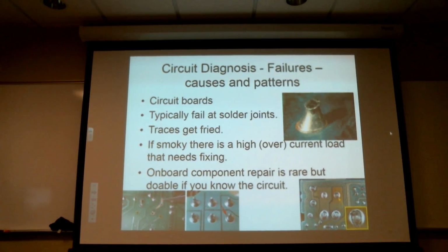disintegrate and people dying. You can kind of smell sometimes, and yeah, okay, might pop the lid, yeah, it's fried. Another broken solder joint. This one here, a torn up trace, also no solder trace pad gone there. That's probably whoever was doing the soldering got it too hot.